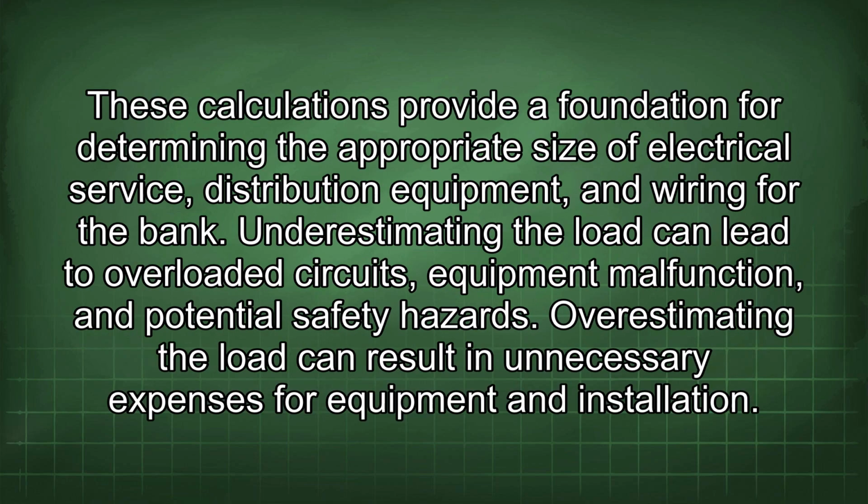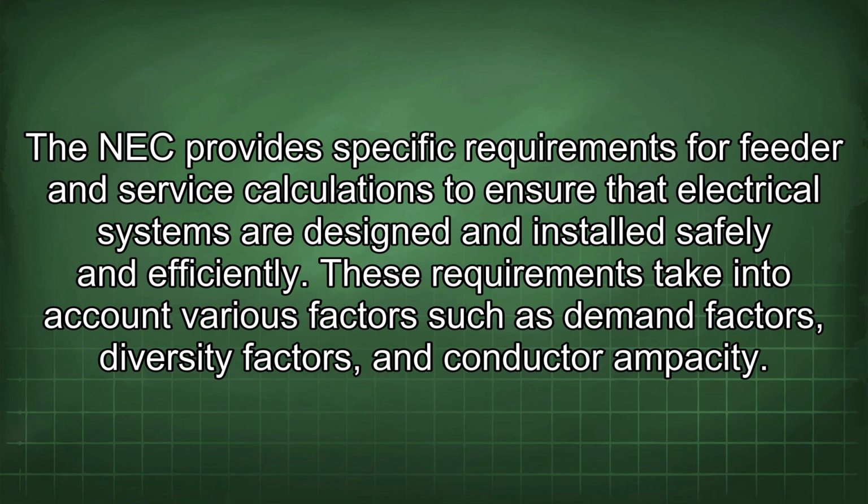These calculations provide a foundation for determining the appropriate size of our electrical service, distribution equipment, and wiring for the bank. Underestimating the load can lead to overloaded circuits, equipment malfunction, and potential safety hazards. Overestimating the load can result in unnecessary expenses for equipment and installation. The NEC provides specific requirements for feeder and service calculations to ensure that electrical systems are designed and installed safely and efficiently. These requirements take into account various factors such as demand factors, diversity factors, and conductor ampacity.